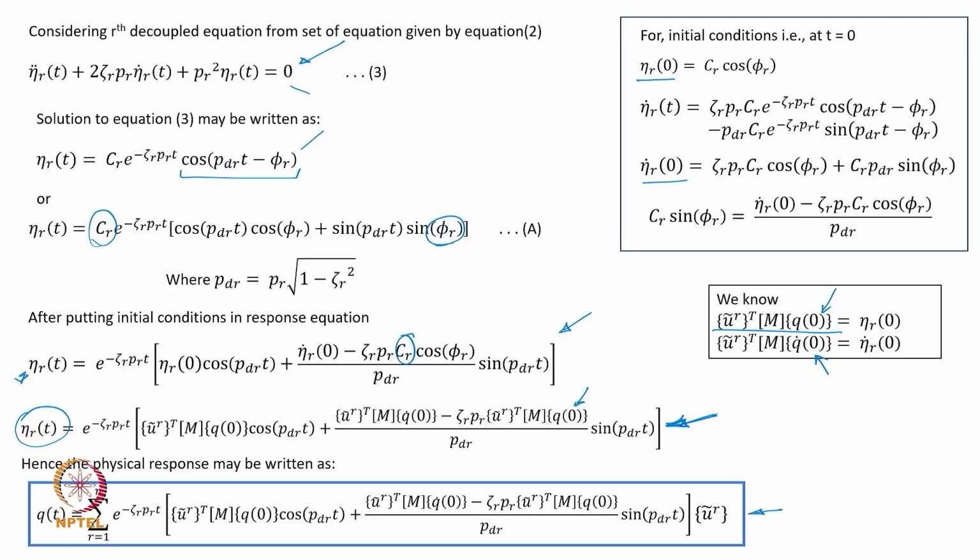If you have understood the undamped case, you simply have to extrapolate this to the damped case. The only thing that is happening is some few more terms are getting involved, but the basic philosophy remains exactly identical. Now, again you can note here the physical response, all these are quite straightforward and known. You know all your eigenvectors, you can find out your individual damped eigenvalues or damped natural frequencies from the eigenvalue analysis.